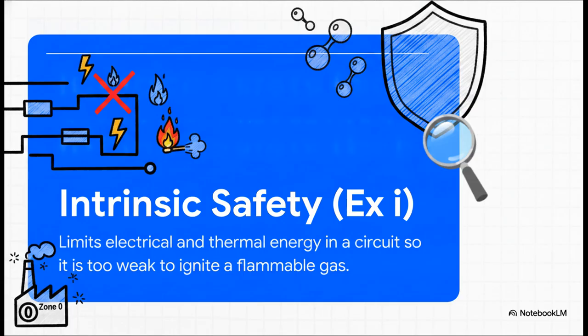Then we have what I'd call the ultimate protection, intrinsic safety, or Ex i. Think of this as literally starving the spark. Engineers design the circuitry so that even if there is a short circuit, the electrical and thermal energy is physically too weak to ignite the gas. Because it's so incredibly safe, this is the primary method used in those highly dangerous Zone 0 environments.